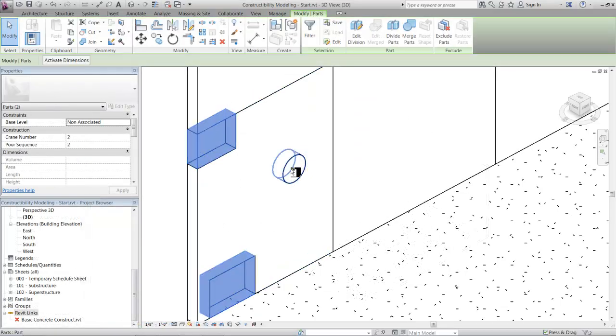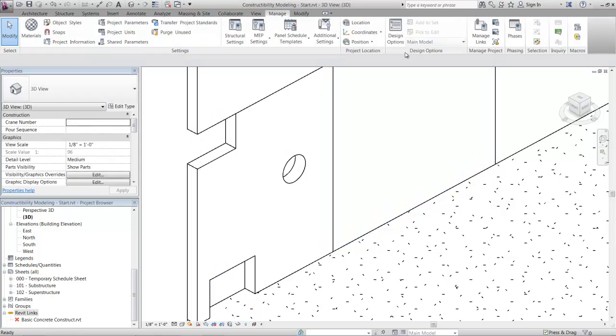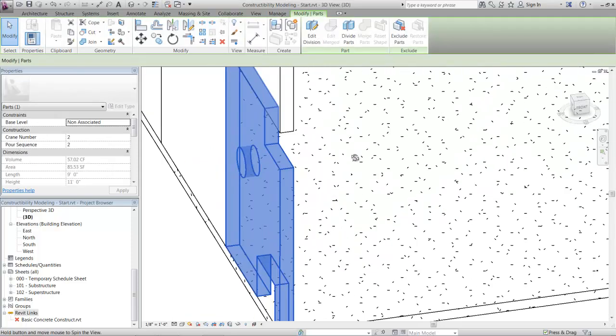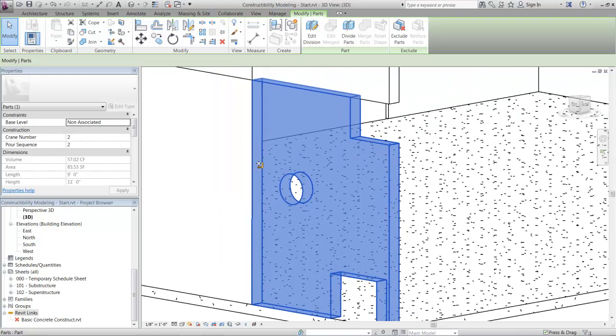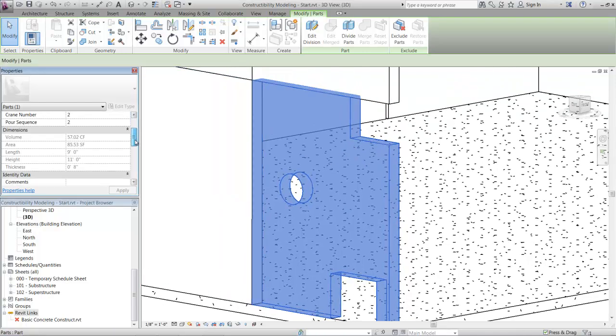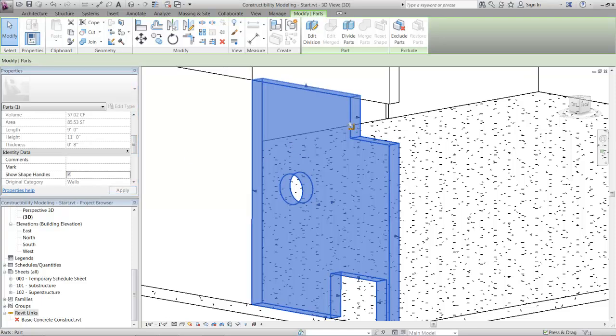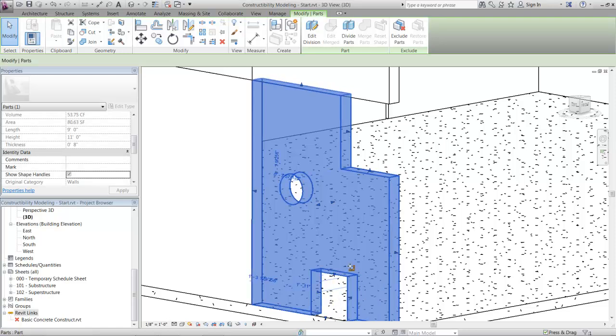However, for a contractor, you may need to understand and investigate the order in which each subassembly is built along with relevant impact on the surrounding trades or logistical equipment. Design intent models can be further modified, dividing slabs into individual concrete pours, breaking partitions to show accurate wall construction, or merging components together to better represent how the elements will be constructed in the field.